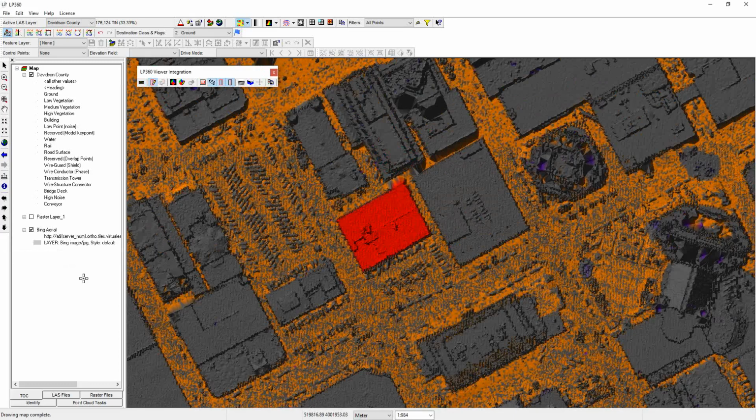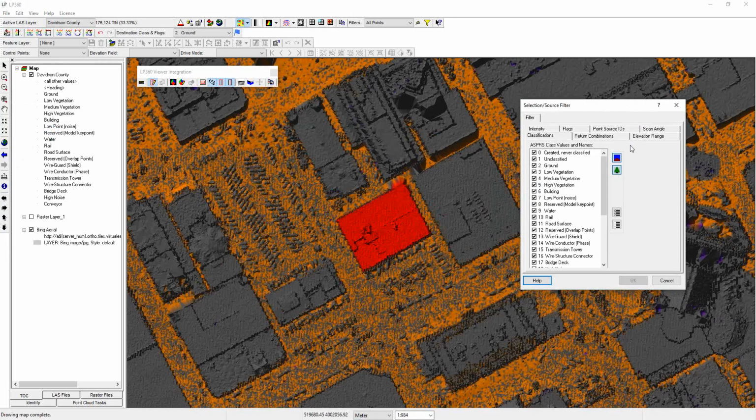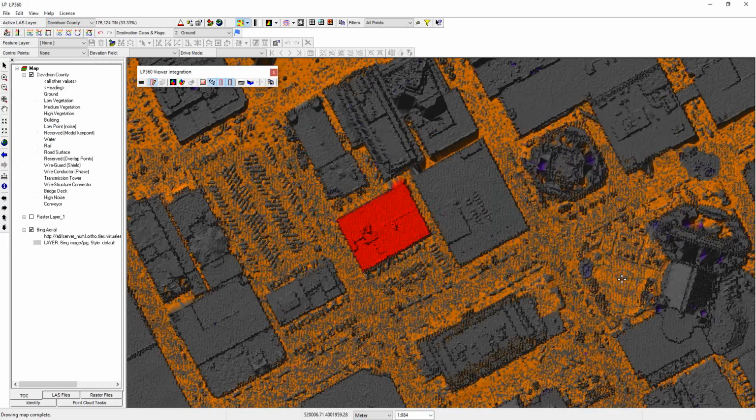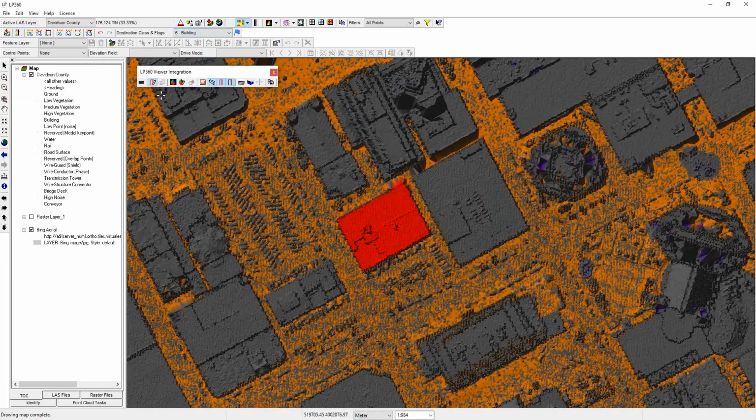A second way to do that, we can do the same kind of from-to manual editing of point data in the map view. Same tools here. I won't worry about the hidden points. It's a different source filter because I may want to classify differently in my map view from my profile view, but I'll keep it the same. I'm just going to classify my unclassified. I don't want to reclassify anything else. My destination class is going to be buildings, so I'm doing building roofs.